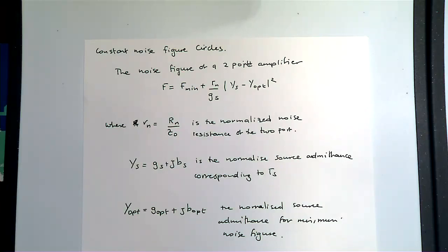Right? Now, usually what happens, and I have to emphasize this, when you receive a transistor data sheet, it tells you these are the scattering parameters, this is Fmin, and the Fmin is achieved at a particular output impedance, output reflection coefficient, I should say.